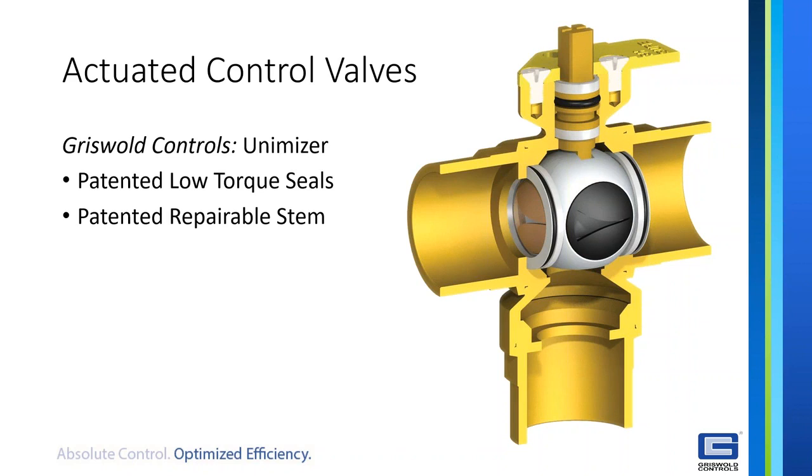So it's quite a jump for your initial purchase cost, and then down the road when you're looking at replacing actuators, because they do wear down before anything else, now you've got an expensive actuator to replace when you could have been using a smaller, less expensive actuator.